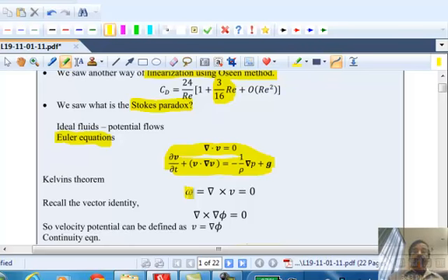And we saw Kelvin's theorem, which states that in an ideal fluid, the condition of irrotationality is always satisfied. That means the vorticity is 0. That is, if you set an ideal fluid in motion, you can never stop it, but you can never get it to move unless you apply only normal stresses, because tangential stresses cannot cause the fluid to move in that idealization. There are no real fluids that obey that kind of behavior. But the solution to the Euler equation gives us reasonably good pressure distributions from which we can calculate lift forces in aerodynamic designs, for example.